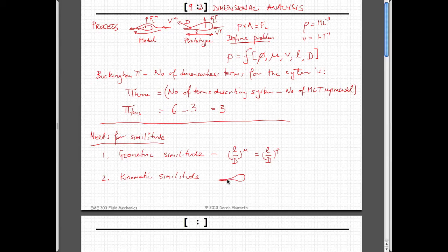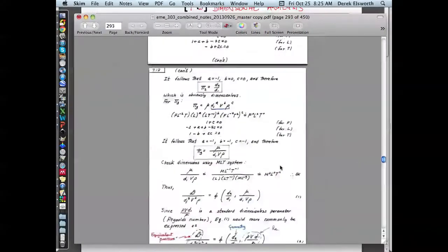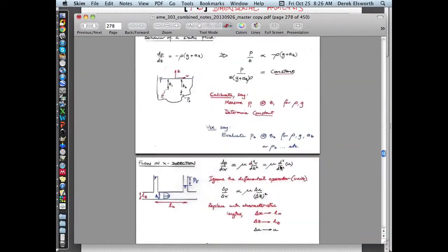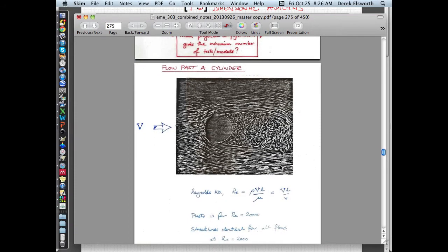And so that's physically saying that if you have your wing that looks like this, actually, let's look. We made the point, if you looked at the materials before, this is the important figure. If you take a snapshot at a particular Reynolds number, which is the key here, the flow pattern around this thing will look like this. You have these little vortices, these little eddies forming here. There's one that's been shed earliest, one that's been shed more recently, and one that's been shed even more recently. This is all going to just move downstream.